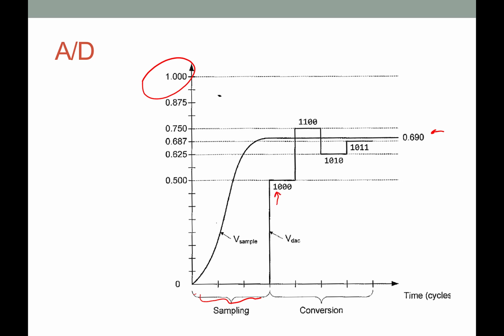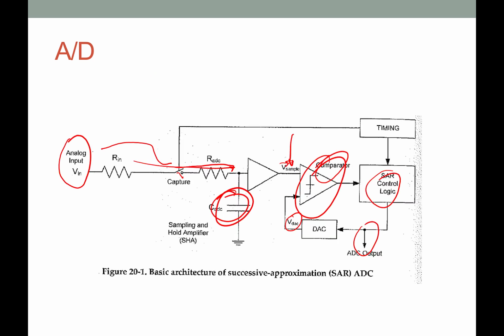Now notice, this is actually going to convert into 4 bits. So we're not just doing 8. Our quantization is not 8, but the idea follows from that previous graph. So this bit is going to represent a half a volt. We take that in and we compare the sample to a half of a volt.